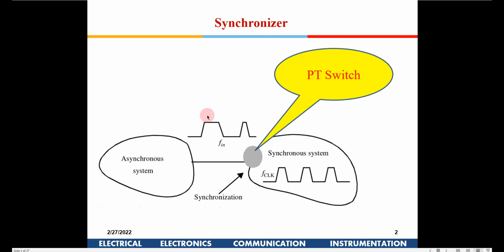It will either push the data towards VIH or pull the data towards VIL. The error will not be eliminated, but there will be no undetermined state. And that error is not very critical, because you are going to sample this at very high frequencies.